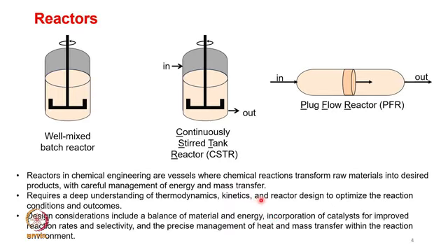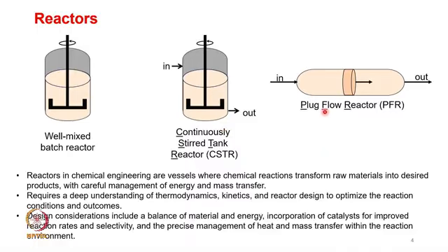Some of these concepts you are familiar with as part of the reaction engineering course, but here our emphasis would be just on the design aspects of it. For instance, how do you compute the reactor volume? Once the reactor volume is computed, you can design the vessel, and what are the particular combinations if there are alternatives possible, let's say if you can integrate the reactor network.